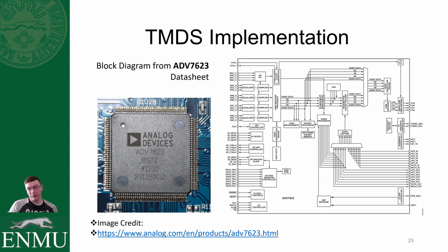It's a multiplexed receiver, and what this does is decode the TMDS transmission lines and convert that into raw, unencrypted RGB values with a refresh rate for your screen. And of course, it separates out those audio packets and recombines them back into a continuous audio stream. Now, there's a block diagram on here. I don't expect you to be able to see that. It's probably too small on the screen you're viewing it on.